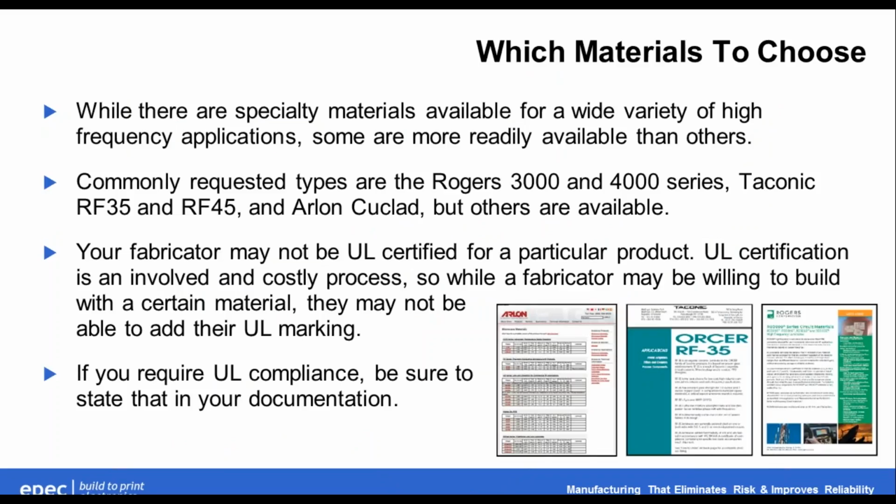Now, which materials to choose? While there are specialty materials available for a wide variety of high-frequency applications, some are more readily available than others. And what we find are the commonly requested types of the Rogers 3000 and 4000 series, Taconic RF35 and RF45, every once in a while Arlon Q-clad or die-clad, but others are available.